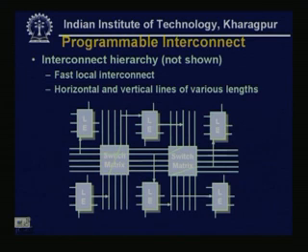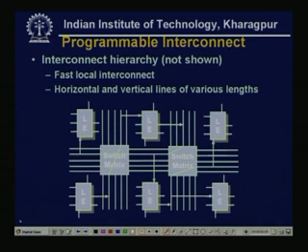This is one general picture. Say this is one switch matrix, this is another switch matrix, and this is another. Say this is my programming part, coming from outside. This is LE, meaning latch enable. So, this line is selected and it goes to this switch, and this is another latch enable.